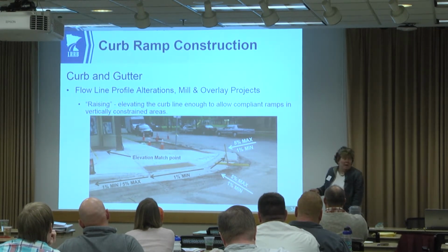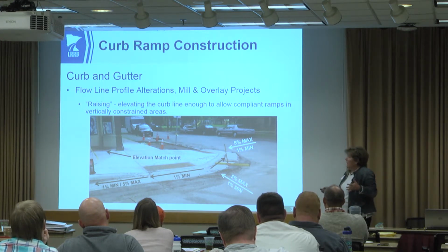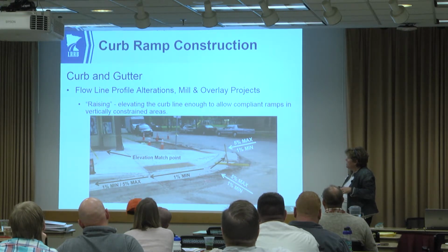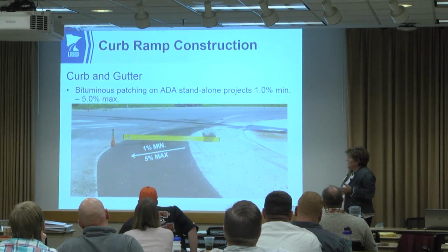Anytime you have a constrained intersection, like where you have a doorway or you have other things that are controlling your elevation, you may also have to work with this. This is showing a very constricted situation where we don't have many removals. You have to worry about longitudinal grades and cross slopes in many directions.